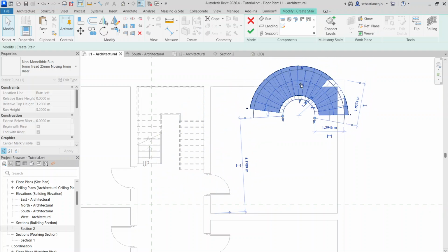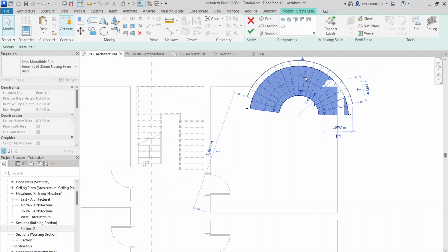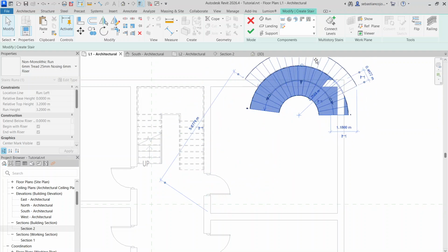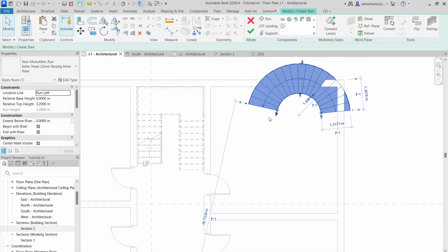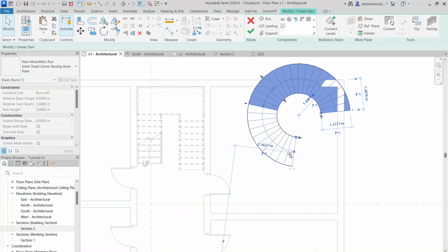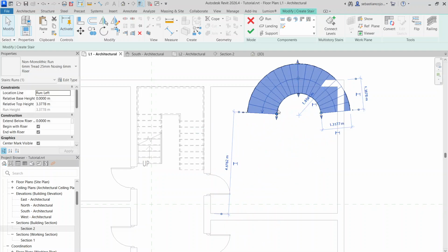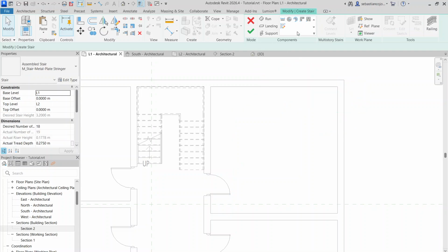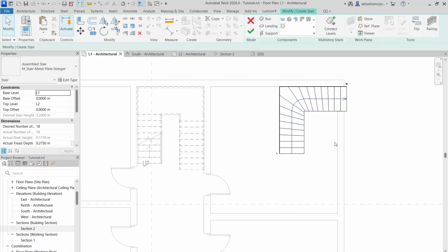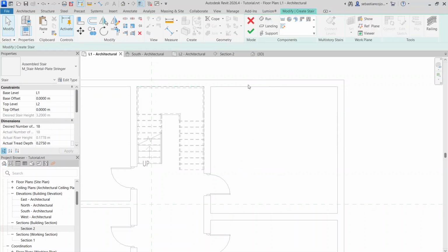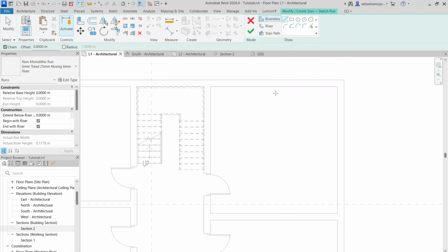You can also adjust how round it is, what's the radius of the stair itself. This is pretty useful. If you want more stairs, you have this handle at the end, and you can have more stairs when you anticipate it, which is pretty neat. You also, I guess, have the L stair, and this is placed automatically. You also have the custom stairs.